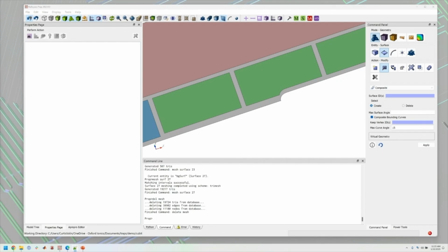So we go to where those commands are located in the script. Sorry, I got lost there for a second. So we're just going to imprint every curve in the top plane onto the surface below, and it knows the surface normal, so it does this imprint with a single line command.